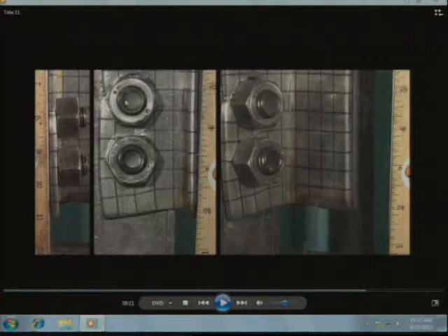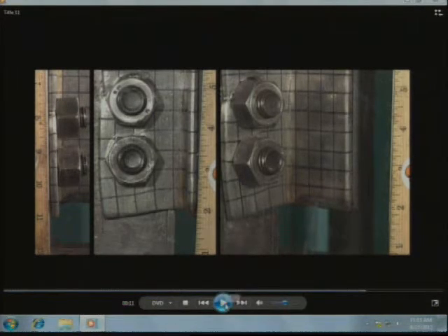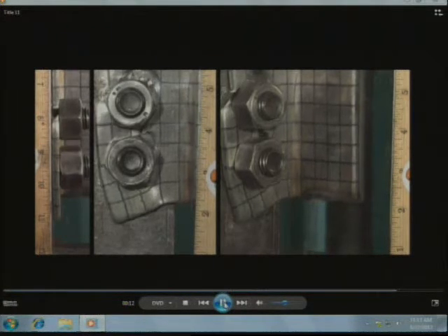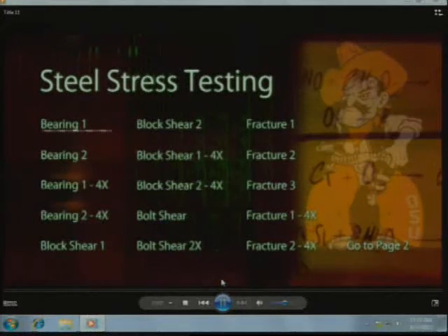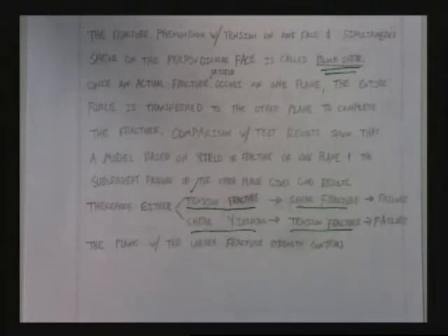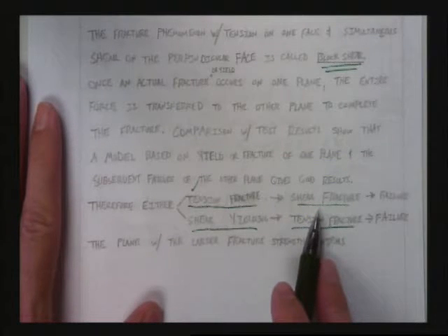Okay, I'm pausing it. It's fractured now. Everyone see the fracture? It hasn't fractured here yet, though. See that? It's very unhappy, all right? But it hasn't fractured yet. So I'm going to keep it going. There, it's unzipped. See, it's unzipped to there. And look, it still hasn't fractured all the way through. But now it has. Makes sense? You believe me now. Oh, yay. Okay. So in that case, what we just looked at was the tension fracture and then the simultaneous shear fracture that happened after that. All right?